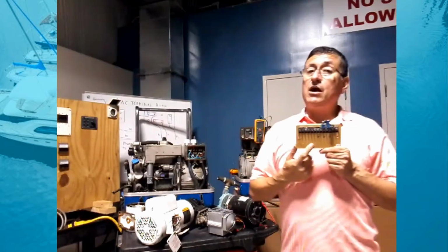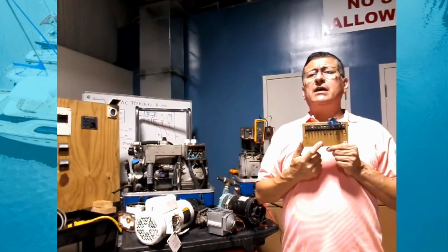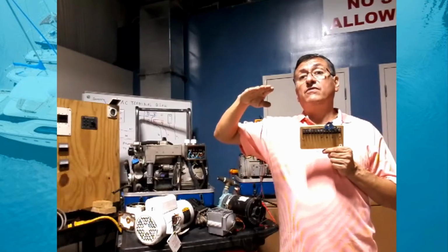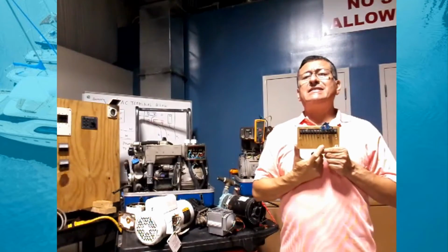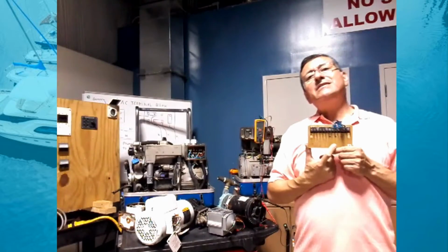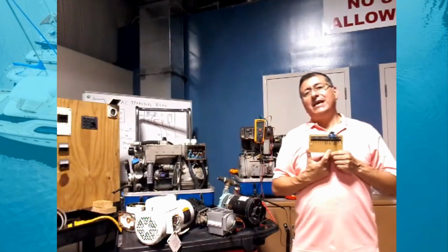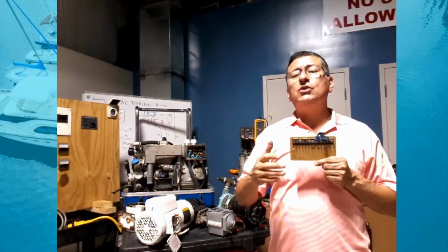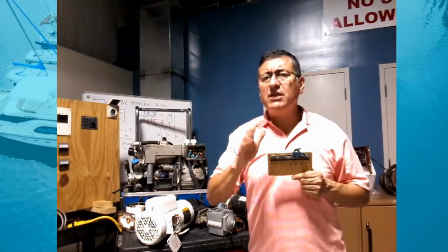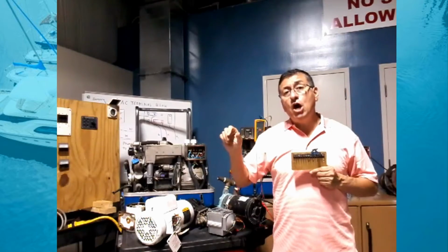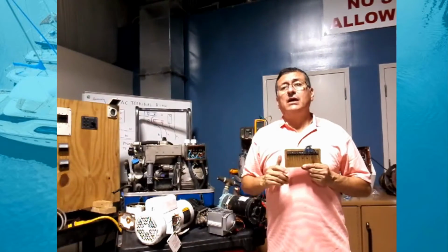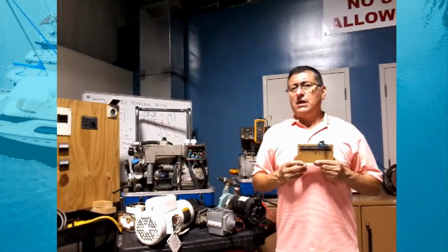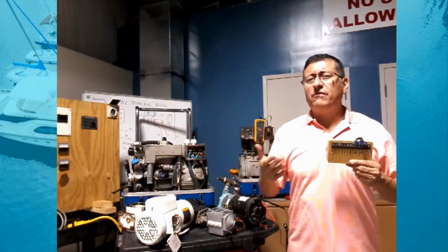Okay, the first one is to calibrate output voltage, higher or lower, no more than 10%. The second one, stabilization, is used to calibrate if the voltage is fluctuating. And the third one is related with the gain. What is the meaning of gain? Gain is the time that the generator spends to recover the maximum RPMs. Normally, when you apply loads on the panel, you hear the generator decrease the RPM a little and immediately recover the RPMs. That procedure normally takes a couple of milliseconds.